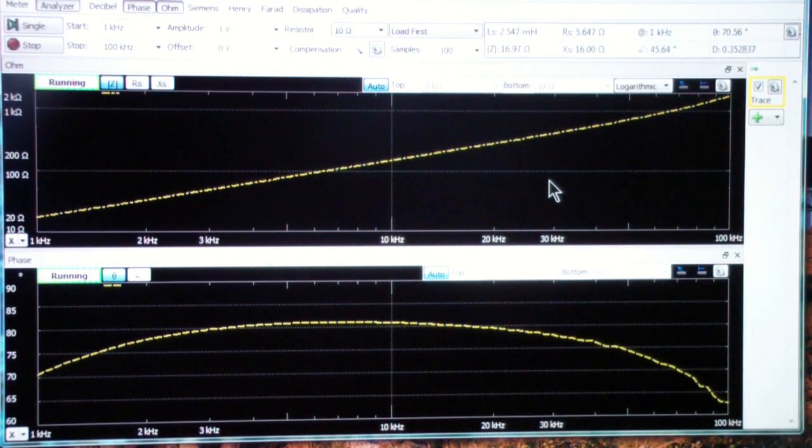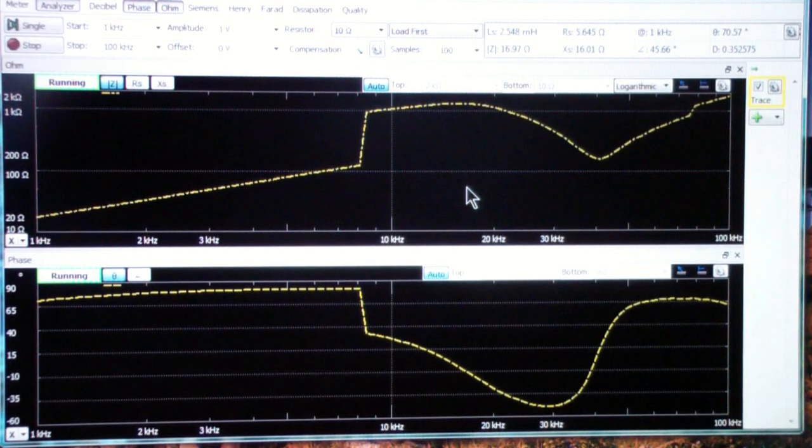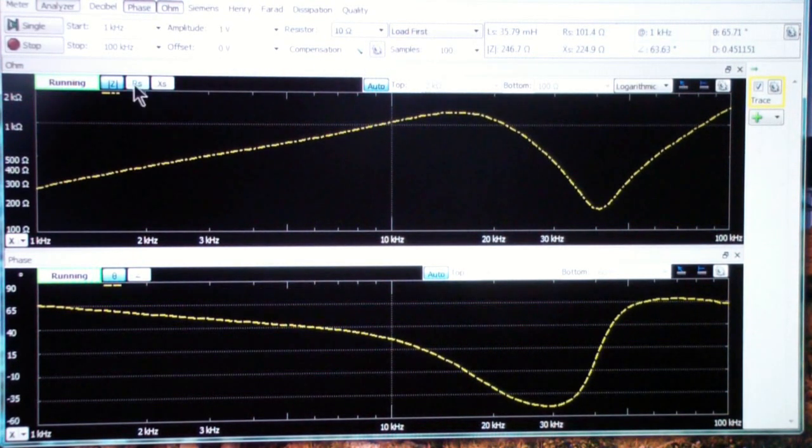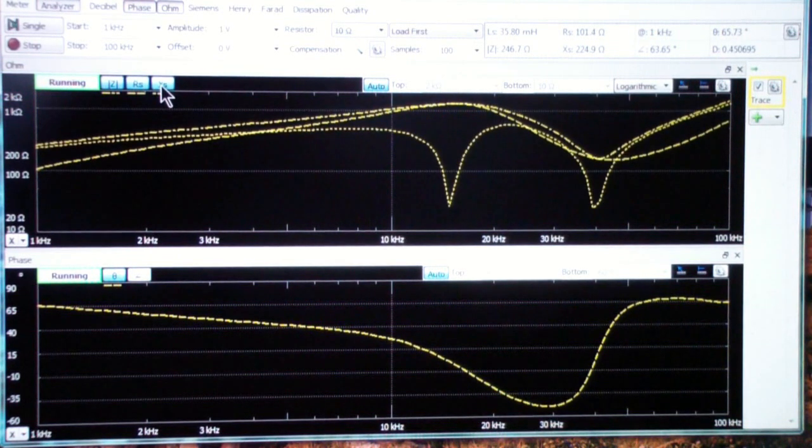But I wanted to point out that in the later days of high fidelity tube amplifiers, a lot of attention was put into how to build a transformer, an output transformer especially, that would cover a wide frequency range and would also provide good efficiency, low parasitics, etc. And when transistors came along, because of their low output impedance, the need for these more expensive transformers went away because they used direct coupled outputs.